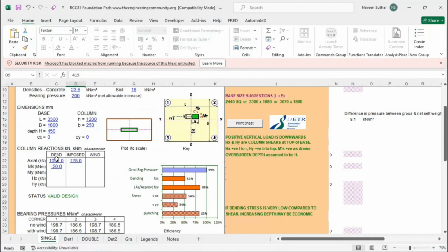If you directly import the loads or load combinations, load cases to SAFE, and do the same in SAFE, it will take a lot of time. So we are preparing the layout first, and then we will design. I think we will have to do very few iterations. In just 2 to 3 iterations, we will get the perfect result.